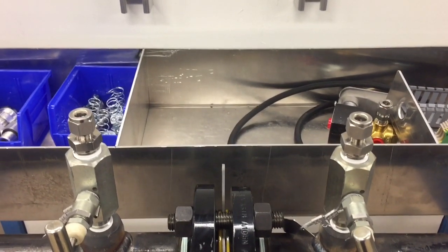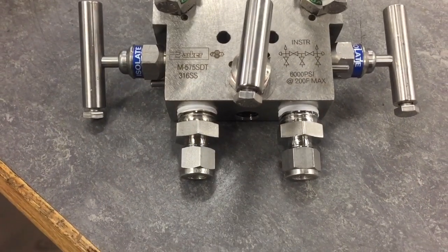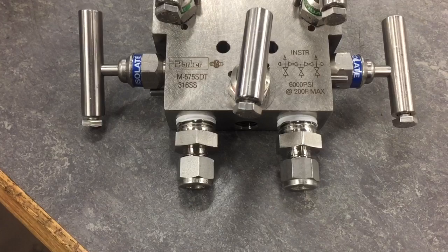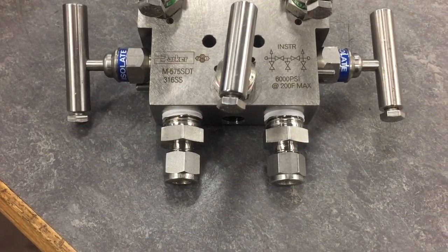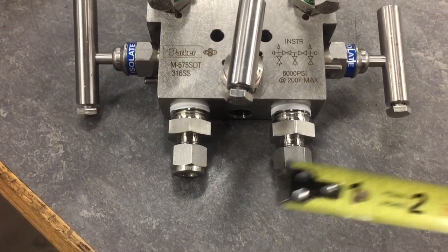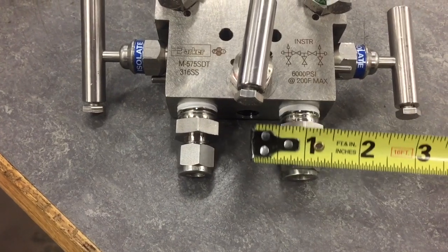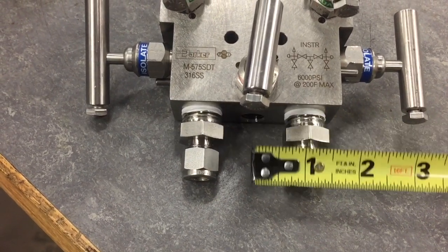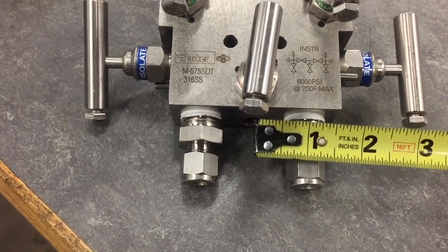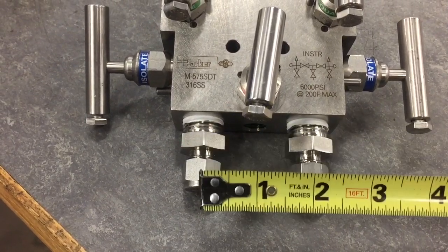Now we need to go over to our manifold and get the measurement. So we had our measurement of 8 1/4. That means we need to come over at least 4 1/8 of an inch, right? We divide that by 2 to get to the center right here. But we also need to take even more off of that, because we don't want to come up to the center of the manifold. We want to 90 up into this fitting right here, right?